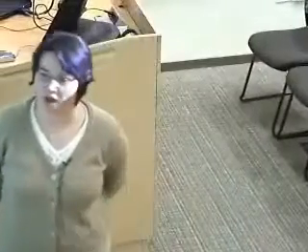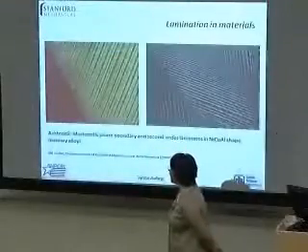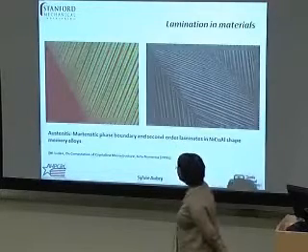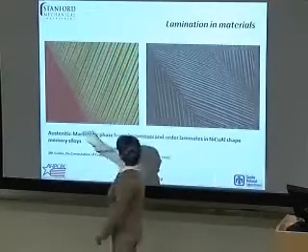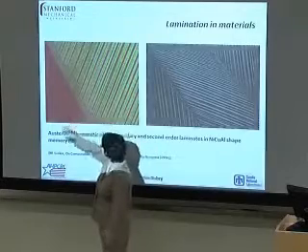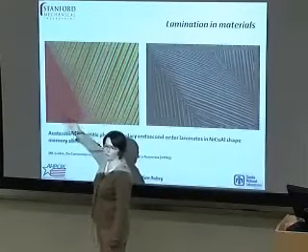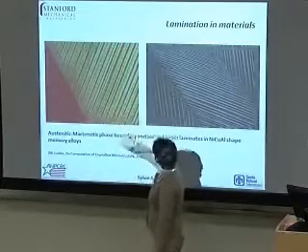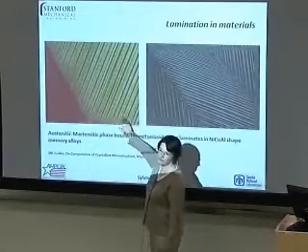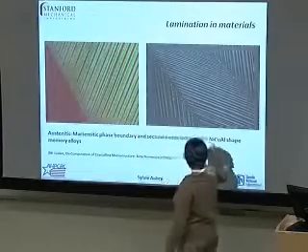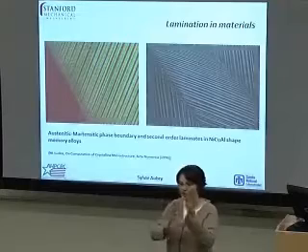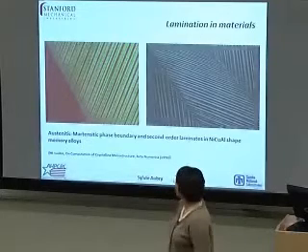works is the following. You have what is called a shape memory alloy, and here it's nickel, copper, aluminum, and it has an austenitic phase, which is mainly a uniform deformation gradient, and it can have a martensitic phase with different variants. For instance, nickel, copper, aluminum has 6 different variants. So these are 6 different arrangements of laminates.